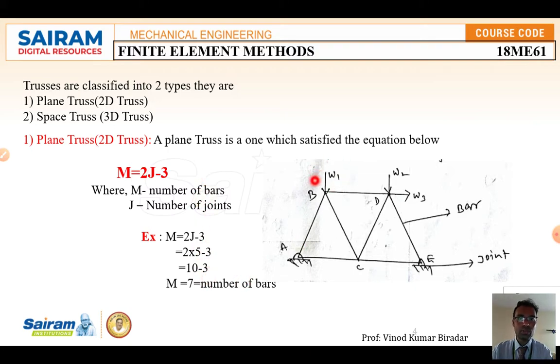This is the load acting. One more thing is that in a truss element, the load should be applied at nodes only. Wherever nodes are there, only there we apply the load. So this is about the 2D truss element.